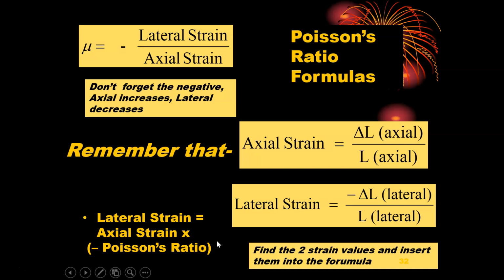Okay, so what is the deformation in Y and Z when a piece of magnesium is 25 inches long and has a 0.75 by 0.500 rectangle end and stretches 0.5? First, we find the axial strain. So the axial deformation divided by the original length. I said that it stretched 0.5 of an inch, so we'll take the strain, the change in length divided by the length, and we say 0.5 divided by 25, and that equals 0.020.